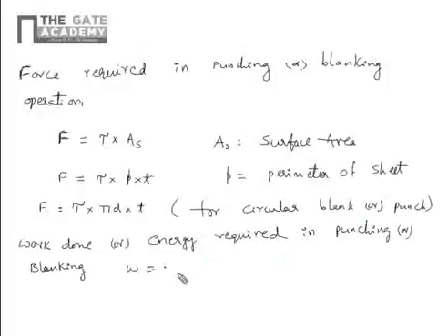W equals force into displacement. Displacement is how much the punch moves. So work done equals force into K into thickness.